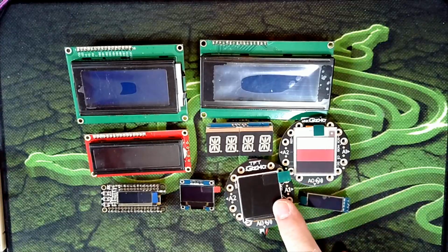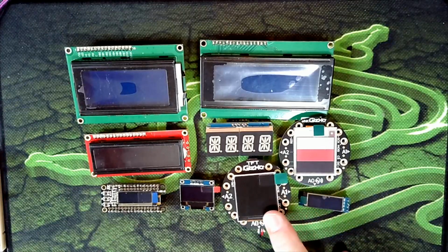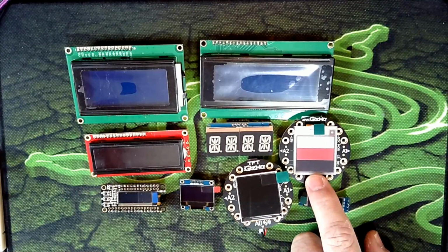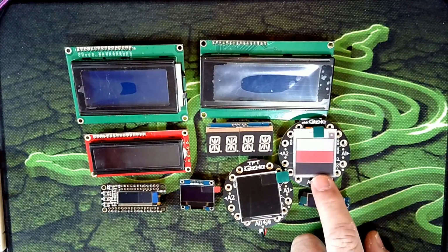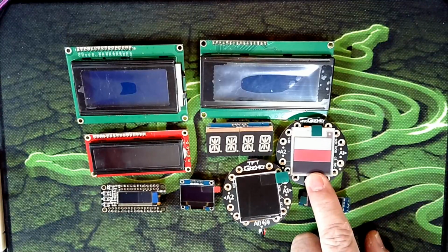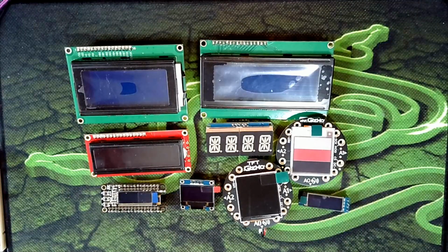Okay, then we have TFT if you want higher resolution and multicolor. And then we get E-Ink if we want extremely low power but limited color resolution. So it's almost like having a black and white image. In fact, they make just a two color version, which is just black and white. It's not as high a contrast of an image and everything else, but super low power. So those are your basic choices.